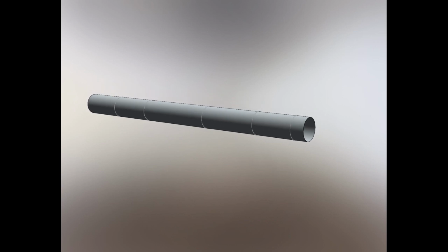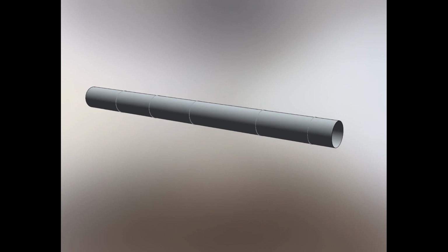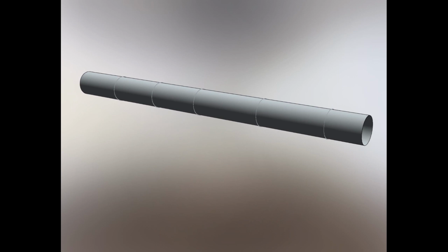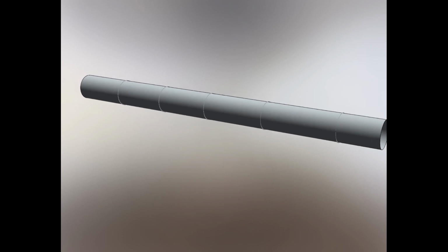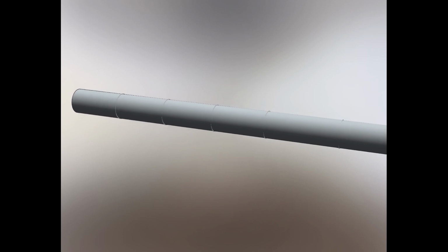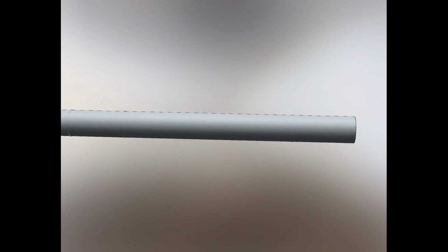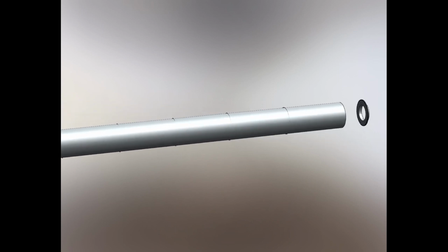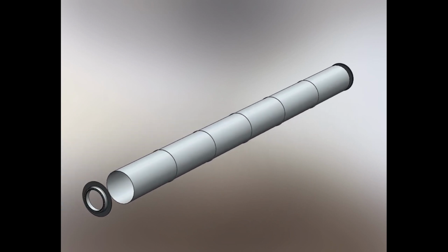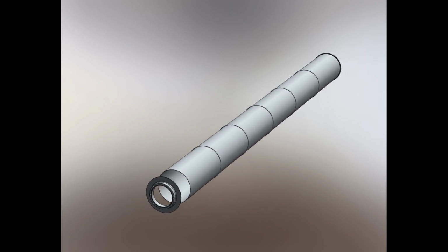Heat is supplied from the outside of the rotating drum and removed by evaporation of water from the wetted inner surface. If the drum is heated by water steam, then the pressure outside the drum is greater than the pressure in the internal cavity. Therefore, to prevent the body from collapsing, the drum is equipped with external rings located at equal distances along the length of the drum, which imparts rigidity to the structure. In the design under consideration, the inner diameter of the ring is 485 mm, the outer diameter is 504 mm, and the ring width is 8 mm.